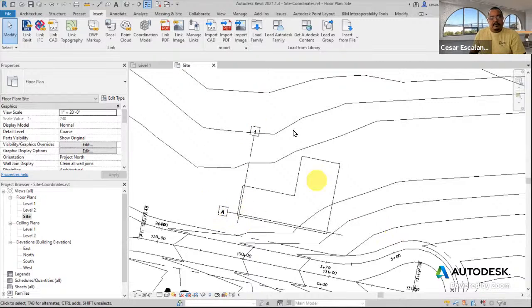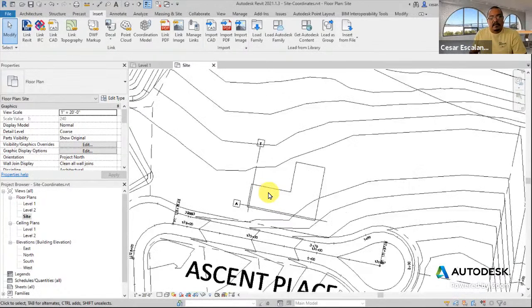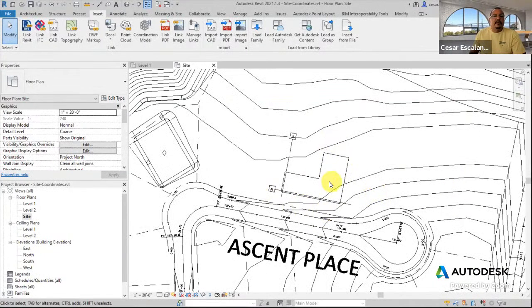And in the DWG, I have a reference for the main grid lines. Because one thing I need to do is make sure that the models have a way to snap and align to monuments in the CAD file. And that's why it's important to have at least the proposed footprint of the building in the survey file. If you are the person defining that survey, then you have to do that work in coordination with the civil person.